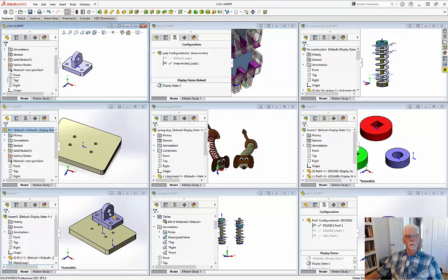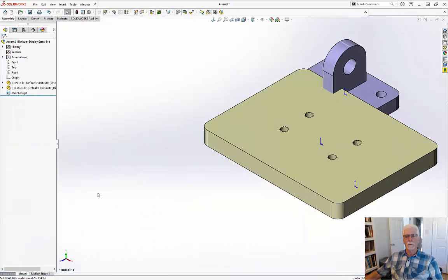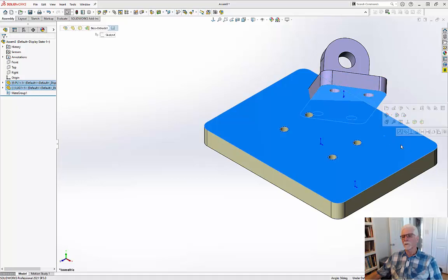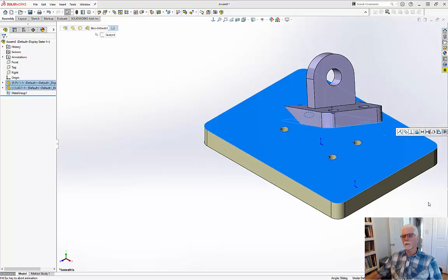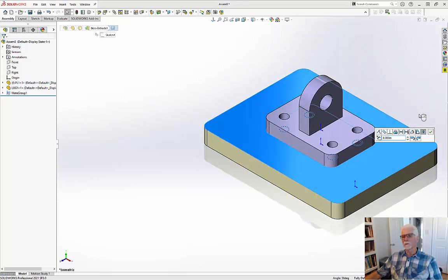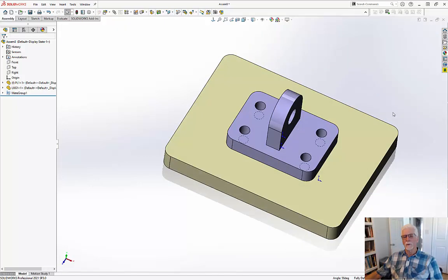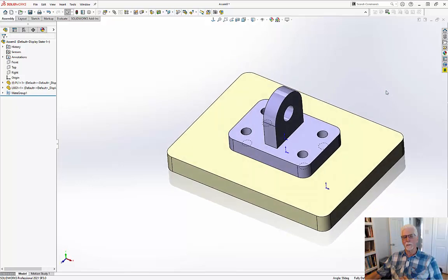And let's drag that into our assembly also. I'm just going to use the famous profile mate, see if this works. It should work. Fairly simple. Everything lines up. All right, so there's our assembly, our mighty assembly.